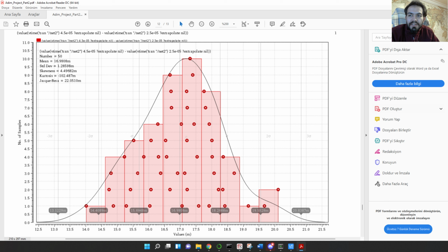And when we actually change process parameters, we can see that our circuit still keeps its monotonicity. So the mean value is 17 millivolts, a bit higher, but the minimum values do not go below 13 millivolts and 20 millivolts, which are quite acceptable.